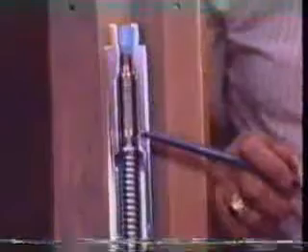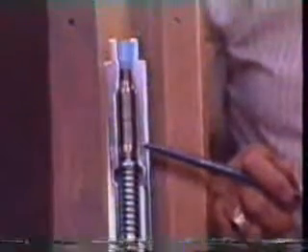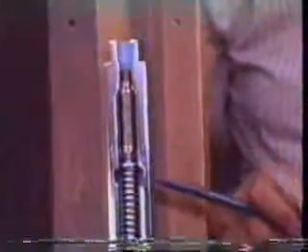The casing pressure now acting on this bellows causes an upward force overcoming the spring force which is used to calibrate the valve. The valve also senses tubing pressure right here at the very small port of the pilot valve. We're not really concerned that this is a small port because no significant amount of gas needs to pass through the pilot. The pilot is simply a control device. So when the pilot is closed, it controls the main valve in a closed position.